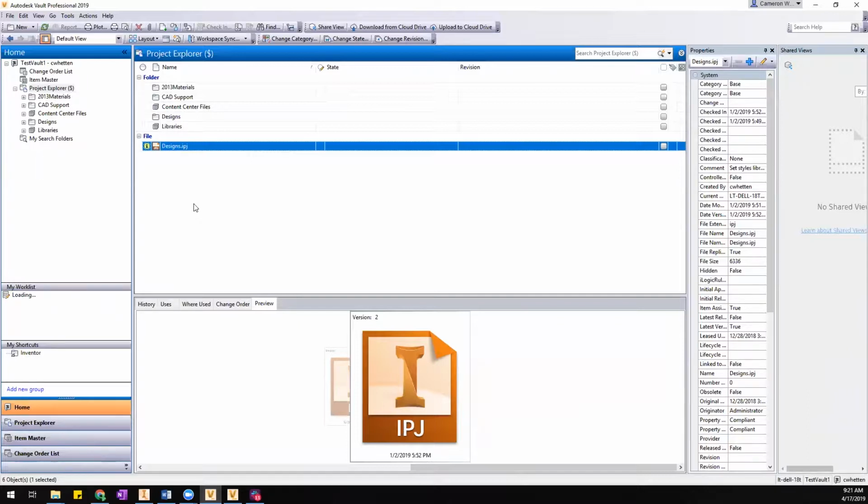So everything is uniform across the board, as opposed to Cameron makes his own Content Center changes. He uses something different for the descriptor, where he uses underscores and I use periods, and he uses capitals and I don't, and it starts getting super messy. And I see that a lot of times when people say, I'm going to give everyone Content Center editor privileges because everyone uses the Content Center. Probably not a great idea.